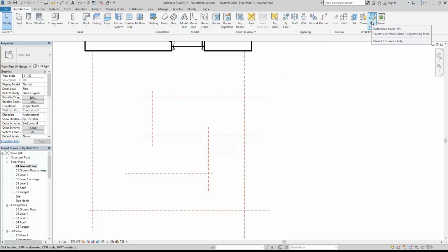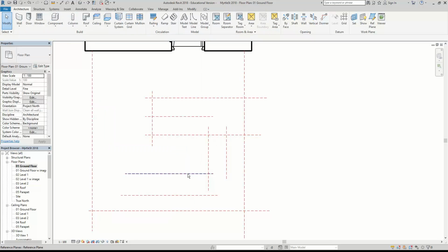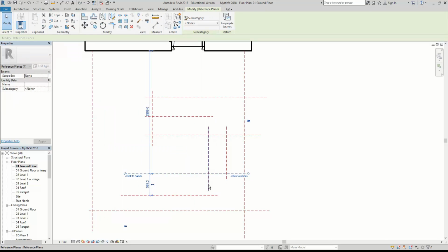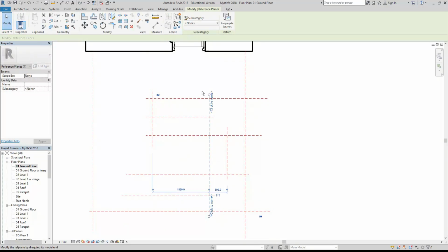So even just to go a little bit further, I'll draw some more reference planes, this time marking the centre line, because remember, that's what you use to draw the stair. So by making it 500 from the edge, that'll be centred. Here I'm drawing centre lines for all of these flights. And then I'm going to keep tidying up these reference planes so it's clear what I'm looking at, and I can see each flight. Oh yeah, you're right, there we go. So we'll fix that.